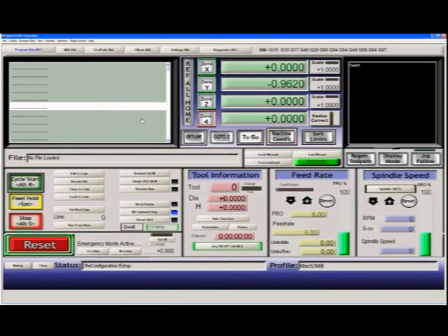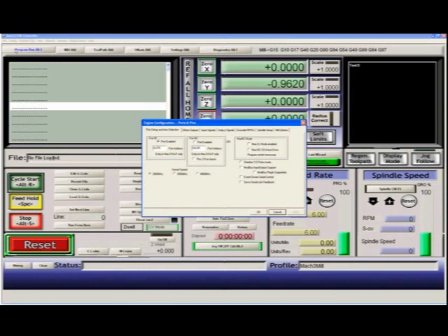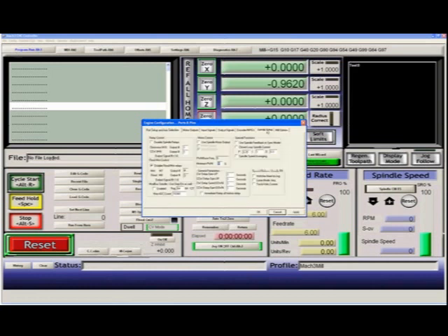Now let's look at setting up a spindle in Mach 3, because that is another problem which is constantly reported. We're going to go to the ports and pins, to the spindle setup tab. Now here under spindle setup, we have several choices for a spindle. First of all, are we going to use the step and direction output to control our spindle motor? Many people don't. Many people simply use a relay. So let's assume we're going to use a relay. You can see that on the left-hand side we have relay control, and it controls the spindle from output signals 1 to 6, whatever you want.